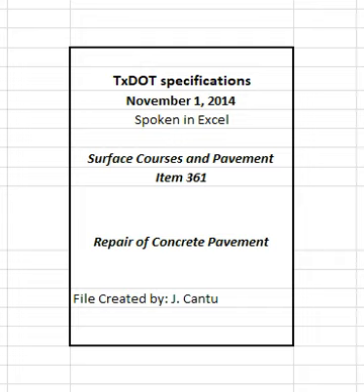Repair boundaries should be square or rectangular with a minimum length and width of 12 inches. Saw-cut repair boundaries to a minimum depth of 1.5 inches. Do not saw-cut longitudinal or transverse steel. If the longitudinal steel is cut, a full depth repair may be required as directed without additional compensation. Remove concrete from the repair area as designated.